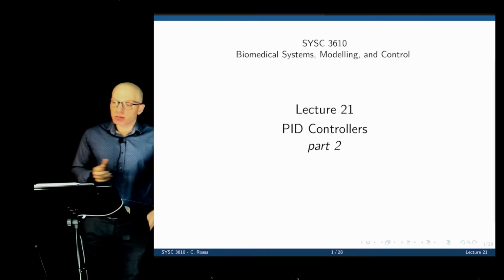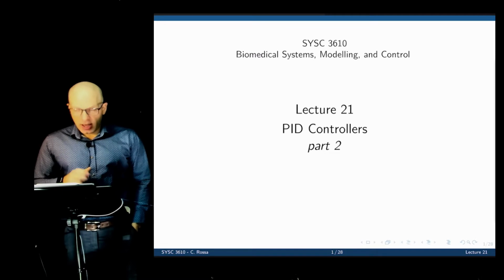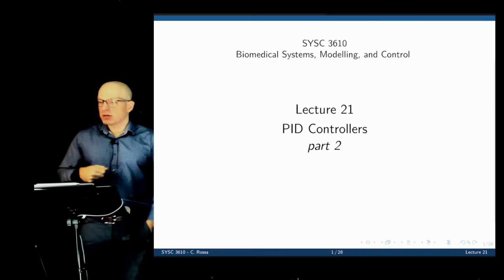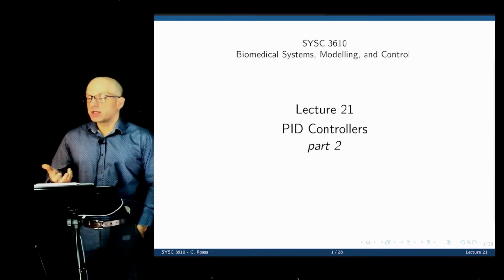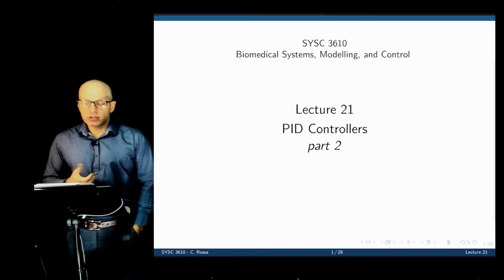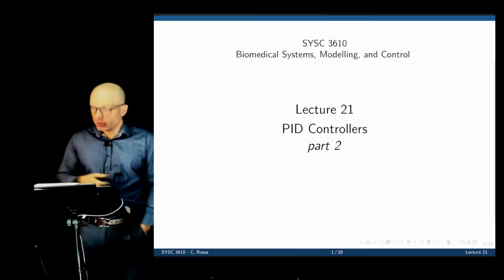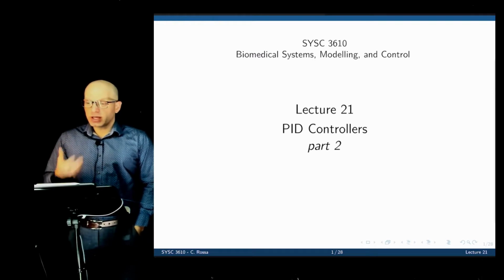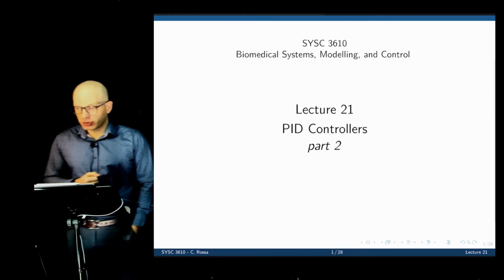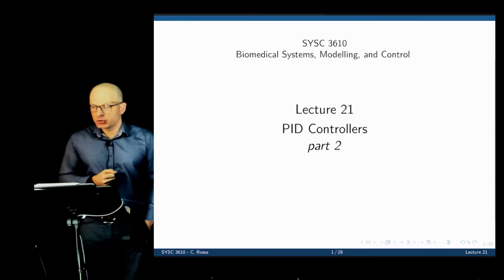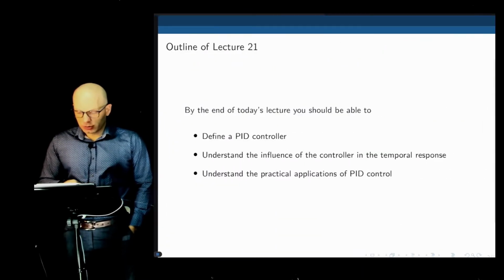But there was one problem with that. The integral gain adds more control action into the game. There is more power given to the plant, and we will start to see some overshoot, which is not always desirable. How do we control the overshoot? Well, that's the job of the derivative controller, the D part, which is the one we are going to focus on today.